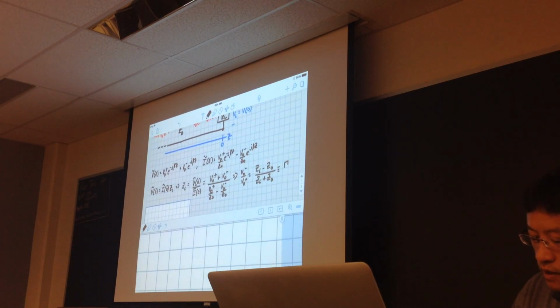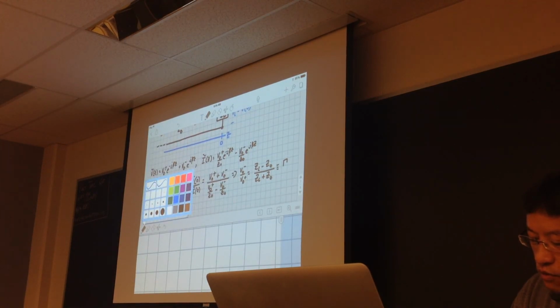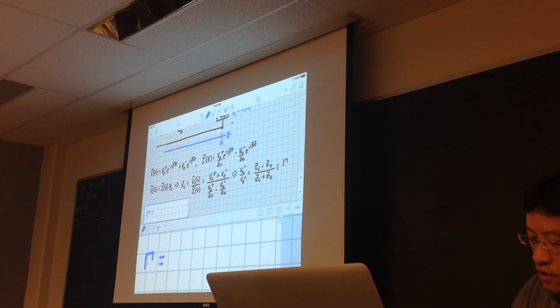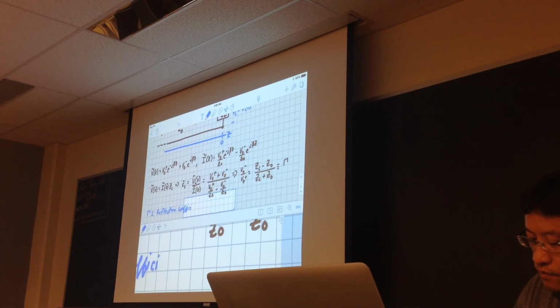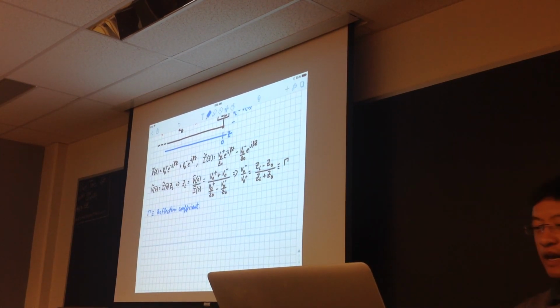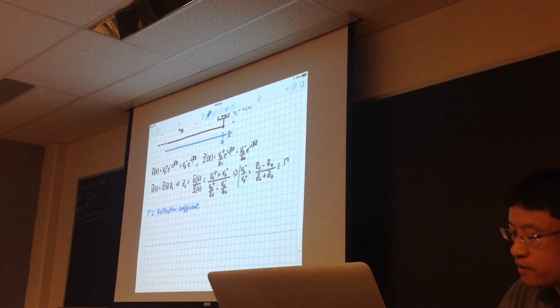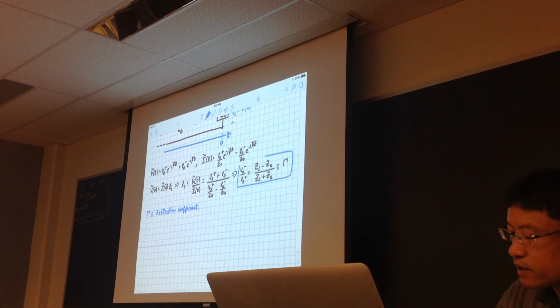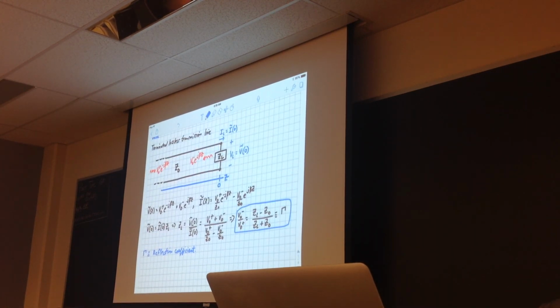Gamma is called your voltage reflection coefficient, or reflection coefficient. If you know ZL and you know Z naught, you can calculate the amount of reflection you're going to get on your transmission line, and that's calculated from this reflection coefficient.